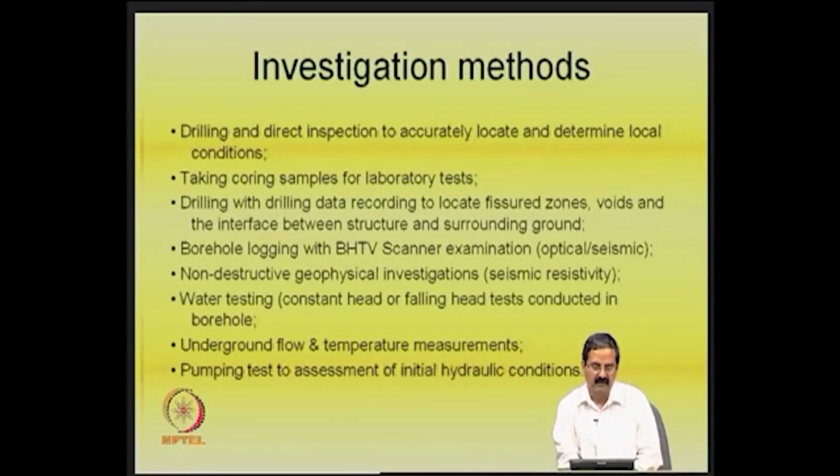Then you should be able to understand the underground flow, how it moves. Say for example, in a particular area, the underground movement of water could be in some localized conditions. One should be able to understand that only that area needs to be stabilized. So, many things, for example, the velocity of the flow underground also influences your choice of the grout, because the grout material should not get washed away when you are trying to do the grouting.